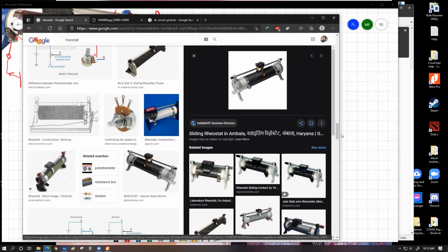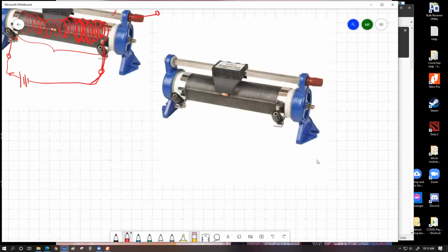So what is happening? We have one copper tip pressing on this side of the wrapping, and the other one is on the other side. The pressure of this copper tooth actually removes a small amount of insulation from the top of the wires.